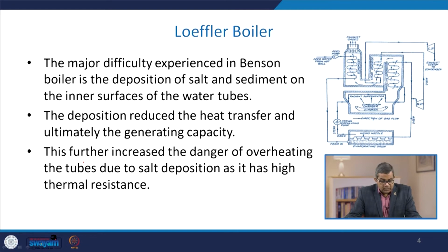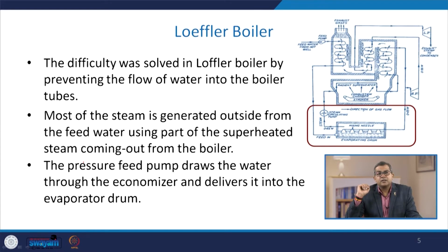If this deposition is there, it will reduce the heat transfer, and ultimately the power or steam generation capacity would be adversely impacted. If this continues, it further increases the danger of overheating of the tubes because of the salt deposition, due to the high thermal resistance.